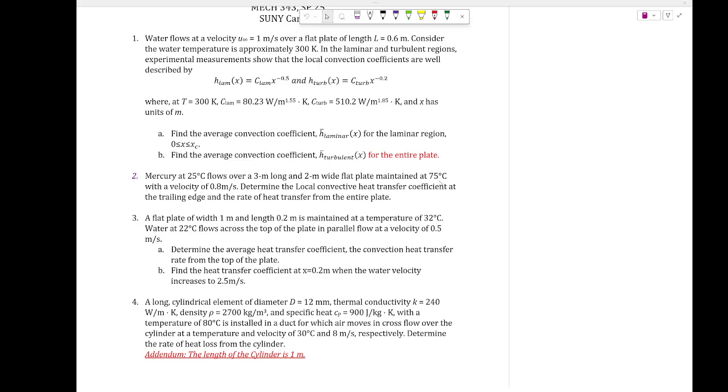From that slope, you should be able to find the value of h. Make sense? You see, these two ratios are the slope, right? So you're going to find the value of h like this, and the temperature T is going to go down, right? This is the equation. And from there you have the A_s and c. m is the mass. You can find the mass of this block, right? You can find the c value for this block from the table, right? And you can find the value of the surface area. The surface area of the block is easily calculated. So can you find the value of h?